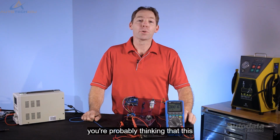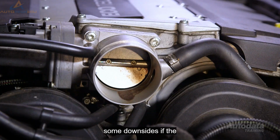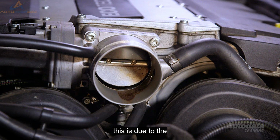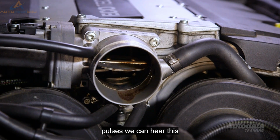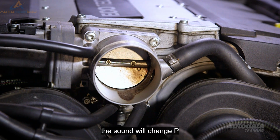By now, you're probably thinking that this PWM control is just brilliant, but there are some downsides. If the duty cycle control is too low for a motor to turn, a high-pitched squeal will be emitted. This is due to the low current flow and the high frequency of the control pulses. We can hear this in a throttle valve motor. As the valve is moved, the sound will change.